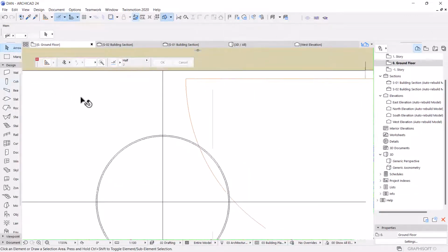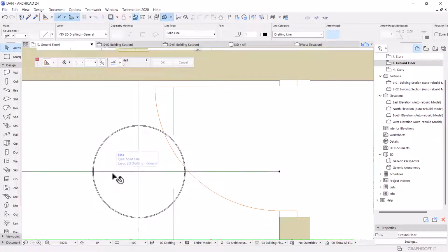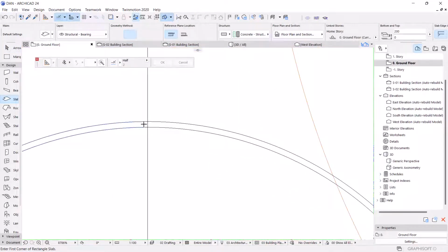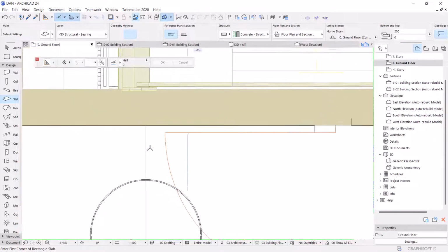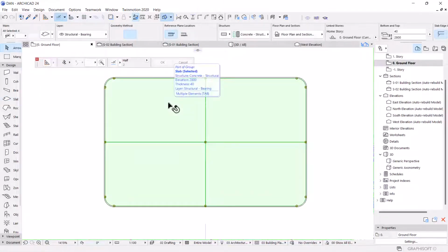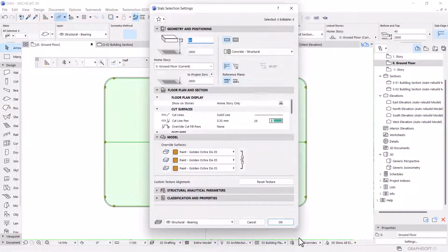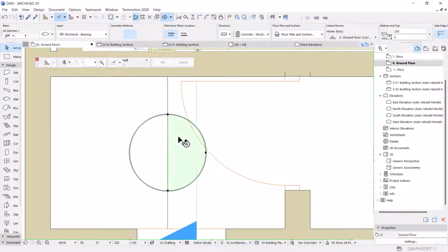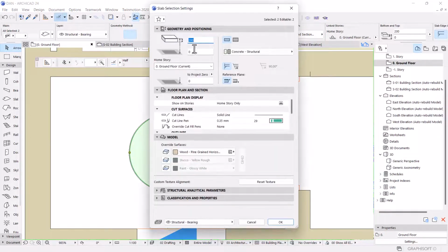Then to make it easier for me, I can delete this line, and I click on the slab, and now I can just hit there and there, then here and here as well. So I could use just the setting of this one. So let me see, 40, 20, 800. Okay, so this one I want it to be 40. Ctrl G, Ctrl T. We're going to do 40.